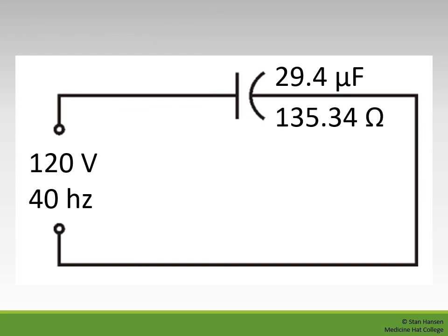The capacitive reactance in this circuit is 135.34 ohms. Since we lowered our capacitance and we lowered our frequency, and they are both inversely proportional to my capacitive reactance, that means my capacitive reactance would be higher, which we can see that it is.